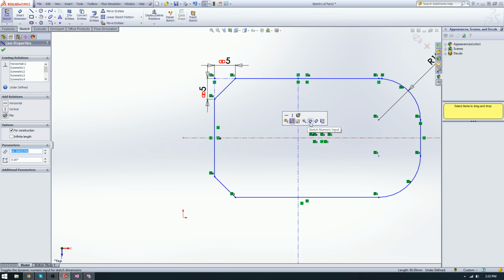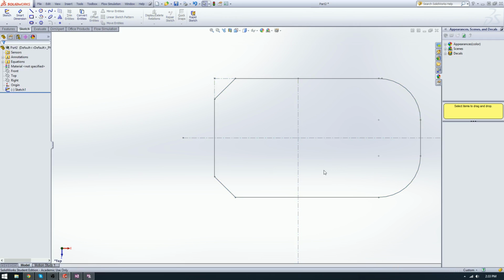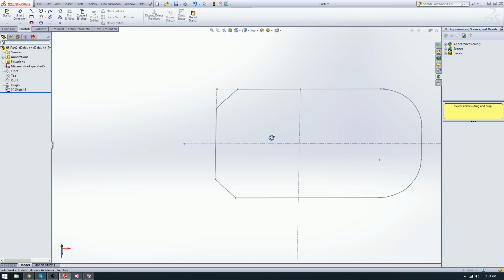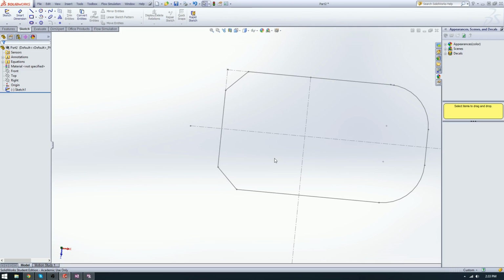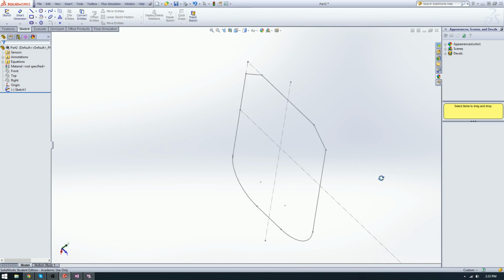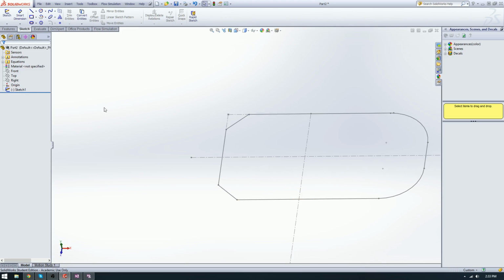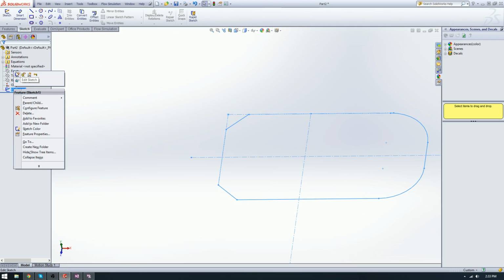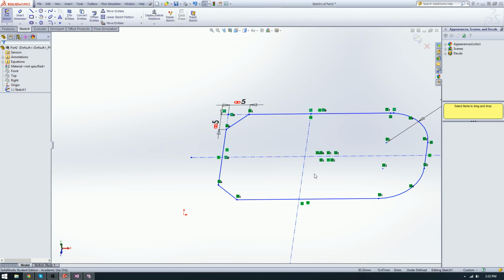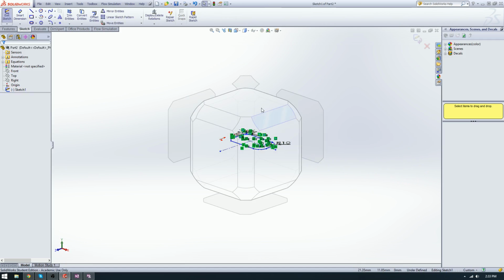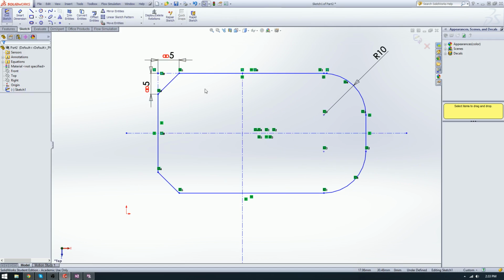What I just did there was an accident, but I'll show you, I guess. If you double click on just the white space of the drawing, it'll actually take you out of the sketch. You'll notice your sketch will turn gray. To get back into it, you have sketch in the window on the left, very important window. Click on sketch, and you can either click edit sketch, or you can right click. It'll pull up the same option, edit sketch. Then we're back into our sketch. Control spacebar, it's a little thing. Okay, we're back into our sketch.